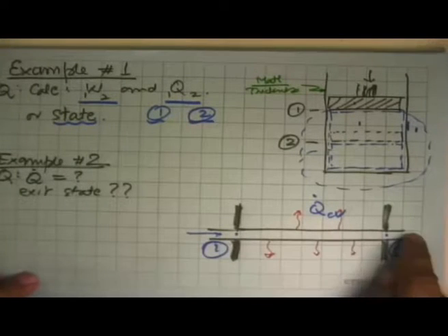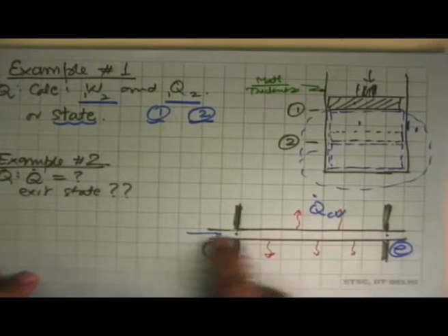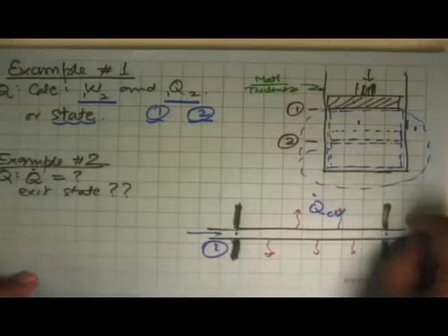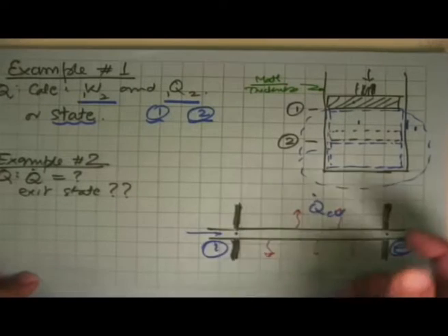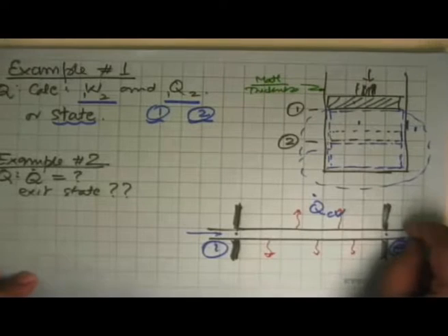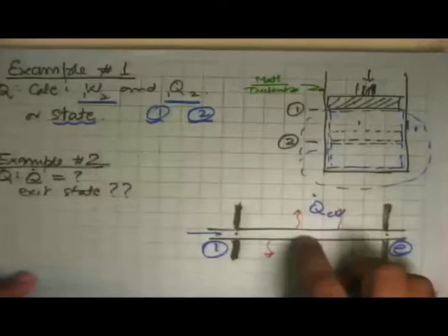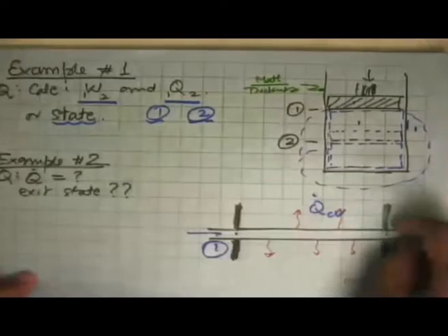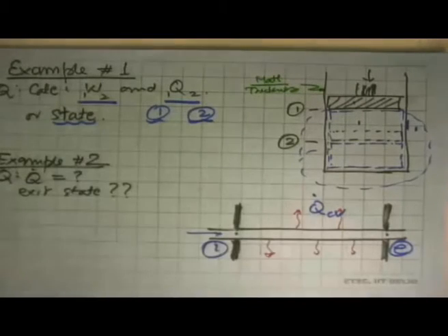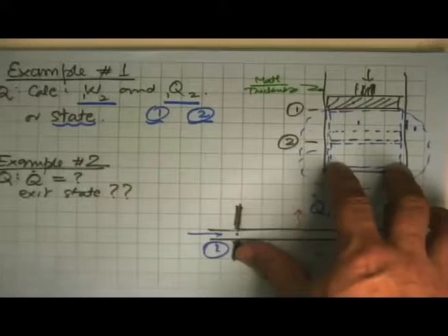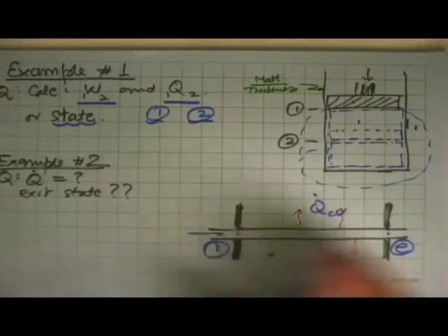If we know the state that it is going to be here, we say, look, this is the inlet pressure and temperature, this is the outlet pressure and temperature. We have to select a tube which will not rupture at the highest possible pressure or temperature. And so let's see what materials we can take. What are those materials which are compatible with this substance, and within that, how thick should it be, and all those decisions start to come in. So what I'm trying to say is that the basic thermodynamic calculation is the starting point for the entire mechanical design of the application.